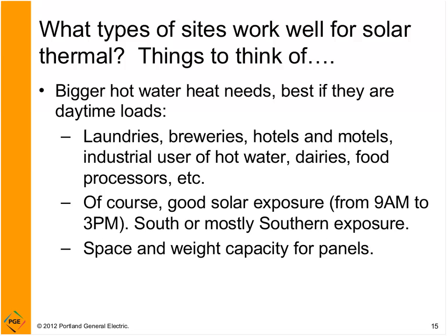Another common misconception is that your solar panels should face due south. That's true for optimization, but if you don't have a true south exposure, it's easy to make a case for, say, south-southwest or south-southeast. If you vary from directly due south by up to 45 degrees, you won't take a big hit on your solar harvest because you get most of the energy that way, even though you're a little off due south. So don't get concerned if you have to orient the panels a little bit off of due south.